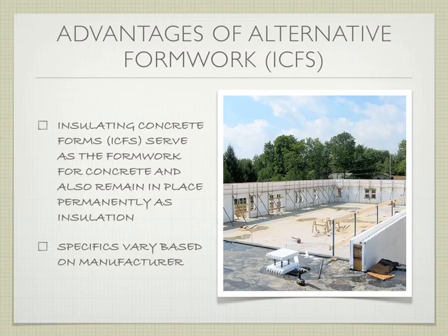Now you can see on those pieces that are coming around, they have a kind of tongue and groove system of teeth that helps them interlock together and not allow the concrete to blow out through the seams. Compared to the plywood formwork, these have a lot of seams, which are somewhat problematic.